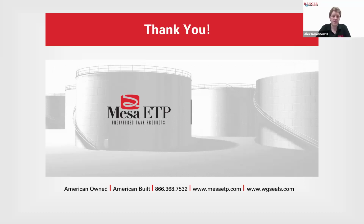Along that same line, it's a good point that not only are we trying to determine if a leak or a release is present, but where it is, and can we target it for more effective repairs, right? In API 653, we've got limits on the amount of seal that can be replaced at any given time with a tank in service. Obviously, out of service, we can do as much as we want.